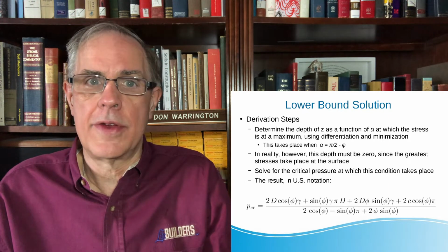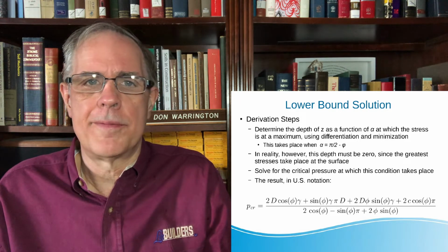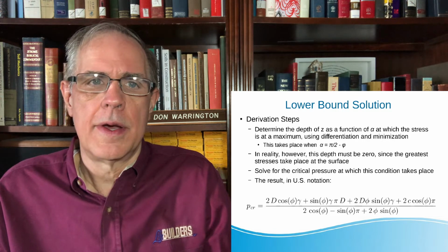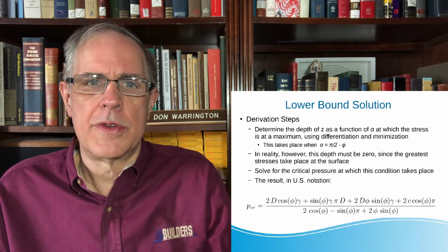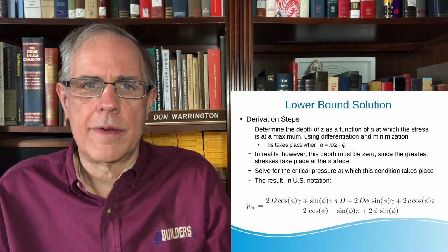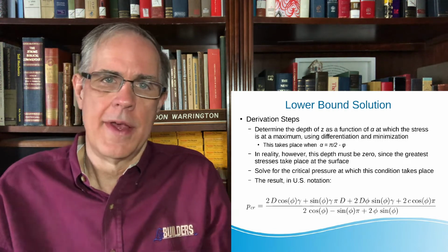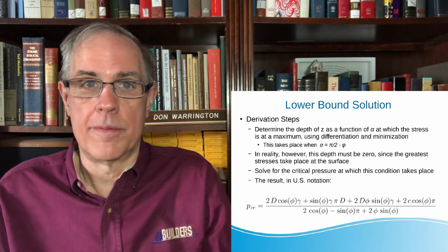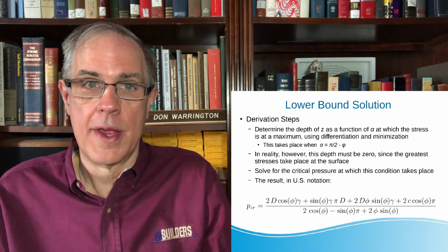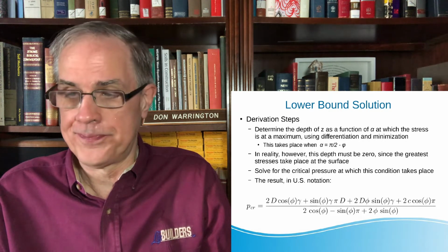And again, like I said, there are a lot of problems with that. Terzaghi uses a simpler solution, there are a number of ways of getting to it, but he doesn't include any friction, and that doesn't make it very useful. The problem with this is that it assumes the foundation is flexible. So there are issues any way you go with it. But in any event, it's a good way of starting at the bottom, and you'll see what I'm talking about in a minute.